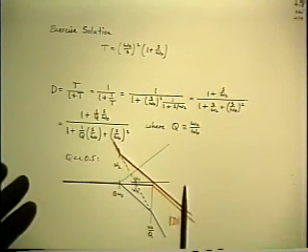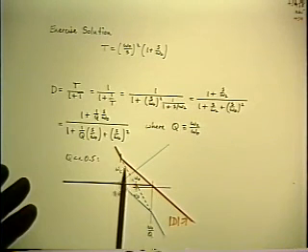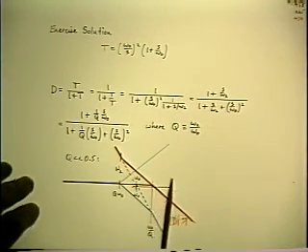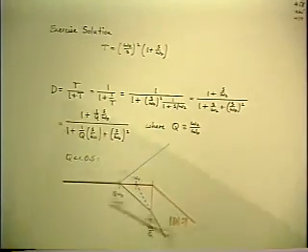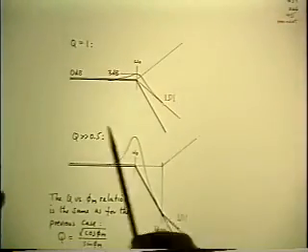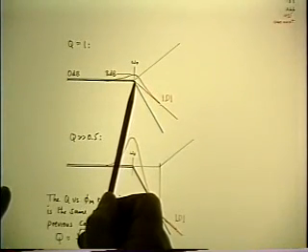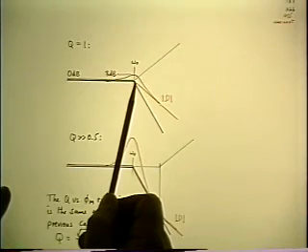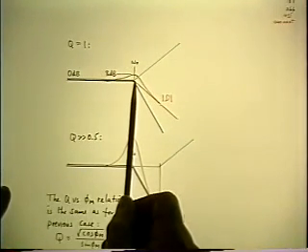Now we can also consider the case where the compensating 0 is not that low, so let's move it out to the case where Q is 1. And if Q is 1, then the denominator, which is the blue asymptotes for the quadratic, will have a double corner at omega 0, and at the same time the 0 in the numerator moves out to the same corner for a Q of 1.